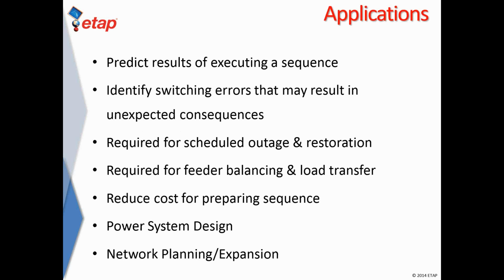There are many applications for SSM module, but predicting the results of executing a sequence is probably the most important one, right? Also identifying any switching errors that may result in unexpected consequence, right? That's why it is always so important that, before the operator is given a switching procedure, it has been tested, verified, and validated by the engineer.